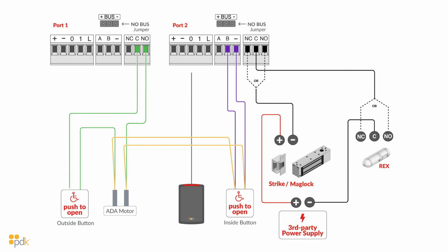It's completely independent of the functional parts of the other part of the ADA system. You still do need to program the lock to release at the same time that the motor is activated, but that's the purpose of the programming that we did in group and system events. That is making sure that the lock releases at the same time that the REX input from either the inside button or outside button released as well.